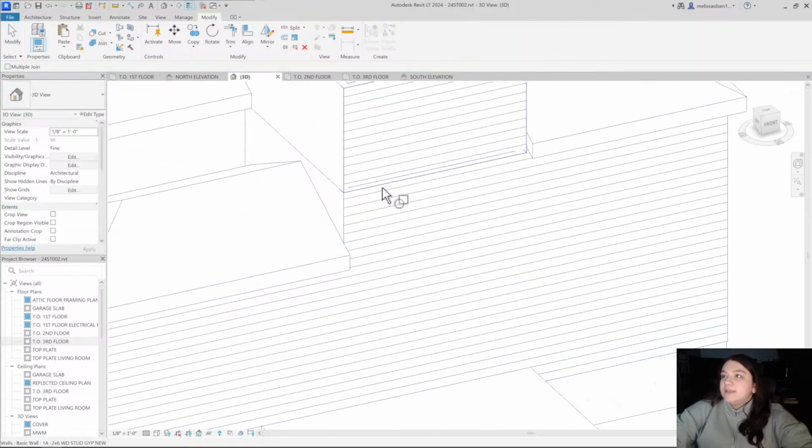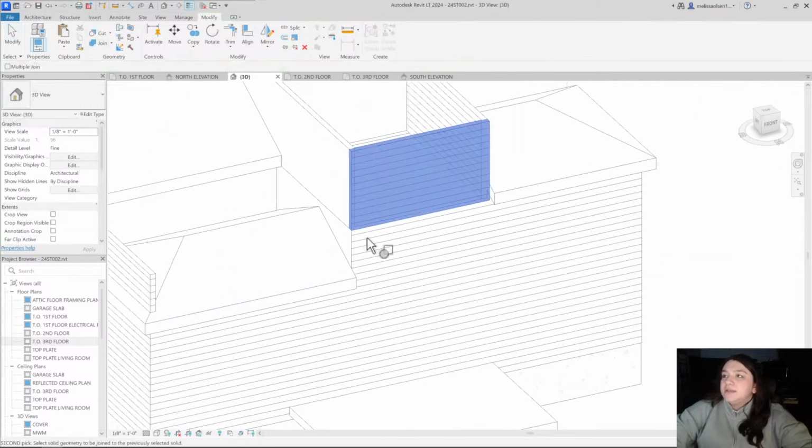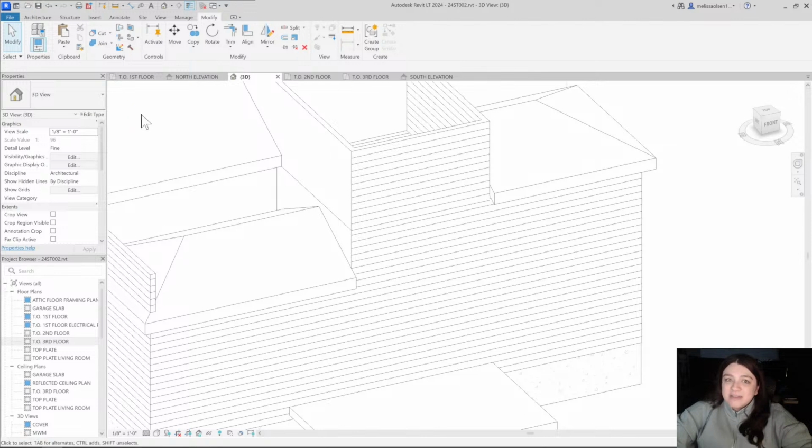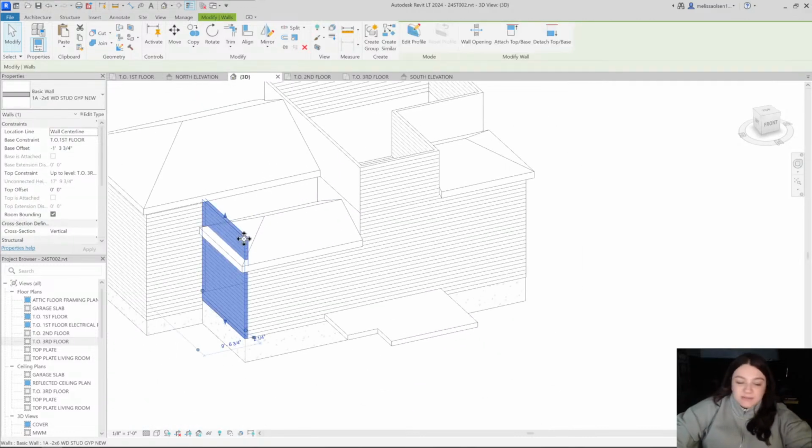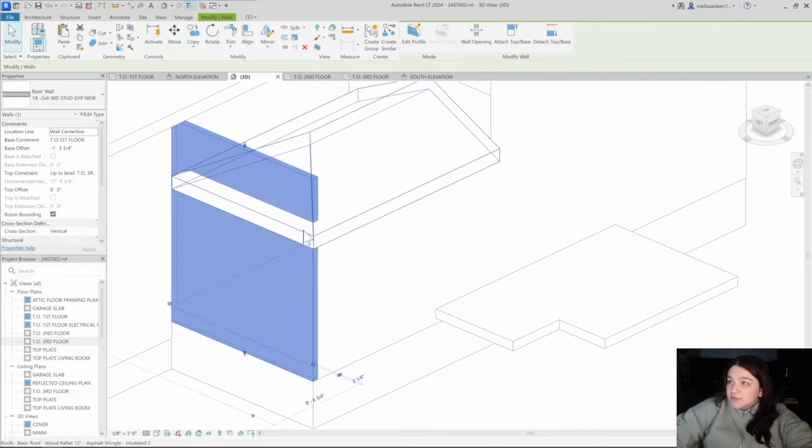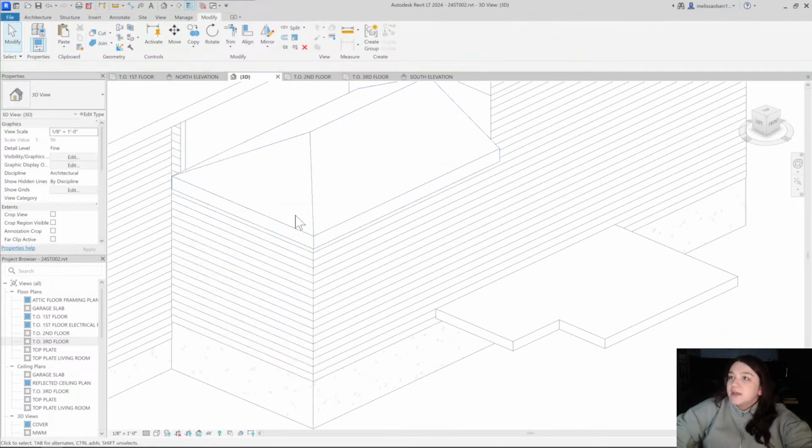In order to get rid of this line, I'm just gonna take this wall and this one, and I'm gonna join them. So there's a little join geometry tool up here. I swear, all of Revit's best, most useful tools, some of them don't even have short commands, which are keyboard commands you can quickly type in to access a tool. And they all are like the smallest icons, which I don't know who decides the size, but some of the best tools are like the smallest icons. So again, I'm just going in, attaching that wall.